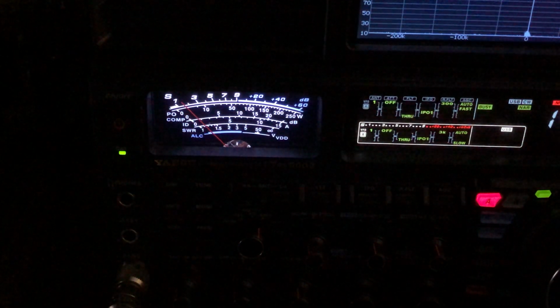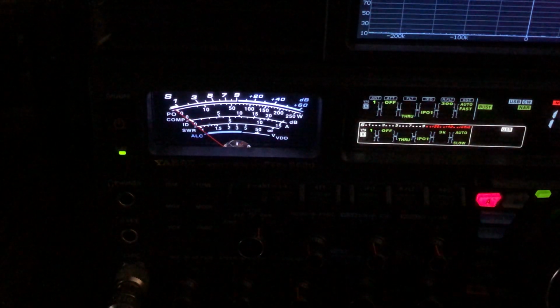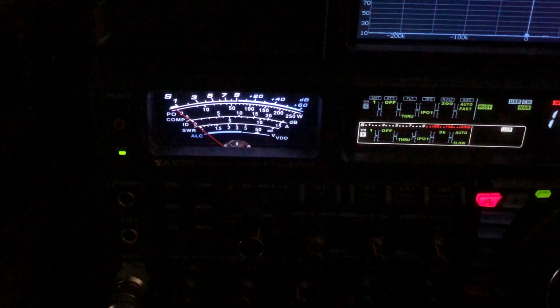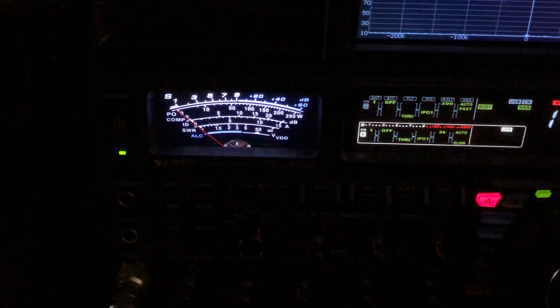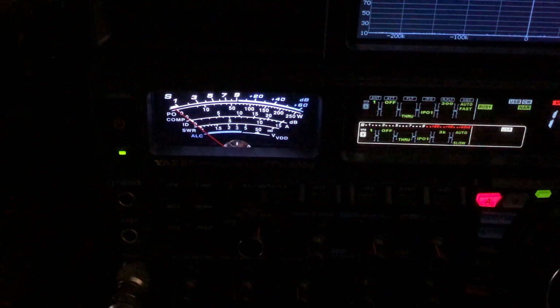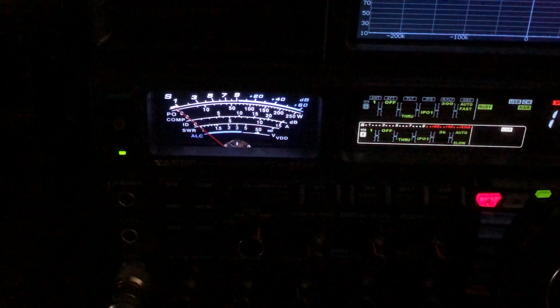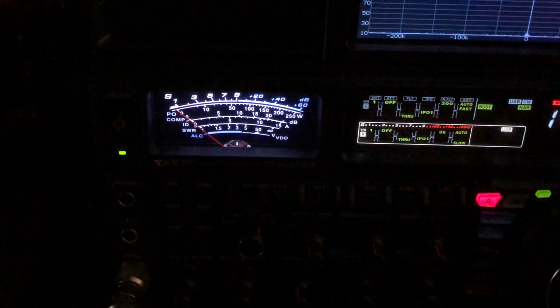Again, most radios are not. As you can see on this one, it's not even the same up and down. I mean, from S1 to S5, it's 2.5 dB per S unit, and from S5 to S9, it's 3 dB per S unit. And above S9, well, the scale is off by 2.